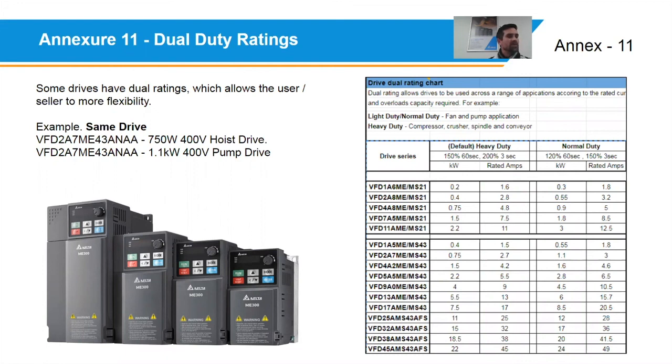Granules or maize, 100% ultrasonic. Definitely ultrasonic sensor, Hadman. We've done quite a lot with grains and maize and things like that. For level control, if it's a liquid, diesel or water or something like that, I suggest a 712 because you don't need to teach the device. You can just immerse it in the water, and if you know the density of the fluid, you can easily work out the level. But with grains and so on, no, you need an ultrasonic sensor, definitely.